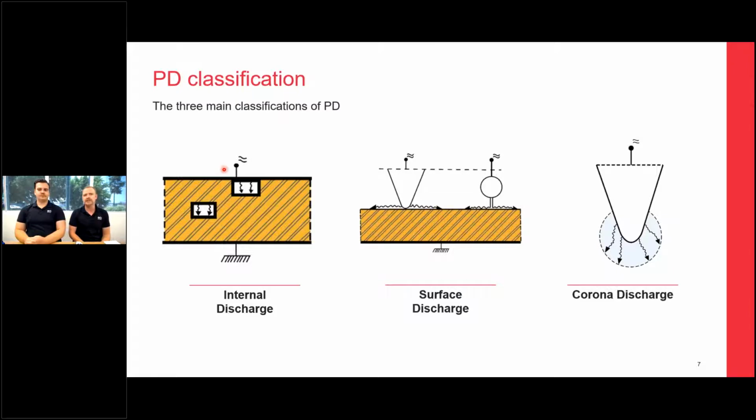It'll discharge at a certain voltage level, and it will start to arc and spark across this gap. When that occurs, it can eat away through your insulation system and eventually bridge out your electrodes, that being phase to earth or phase to phase, and cause the HV failure.